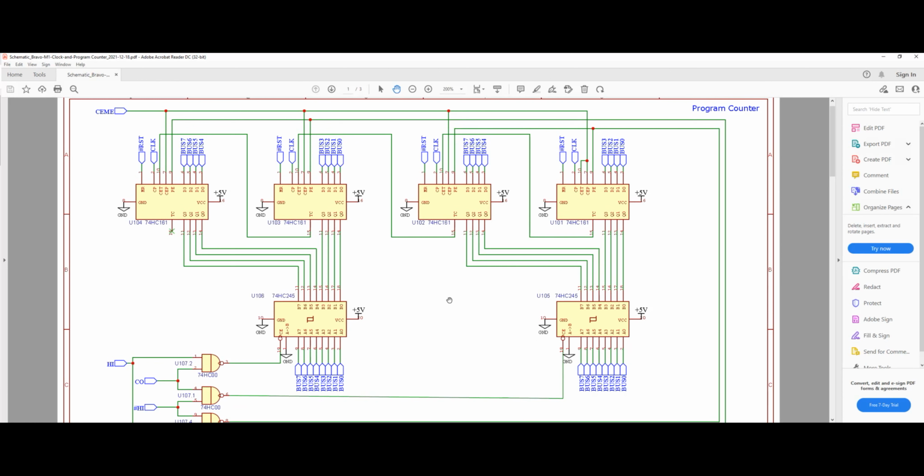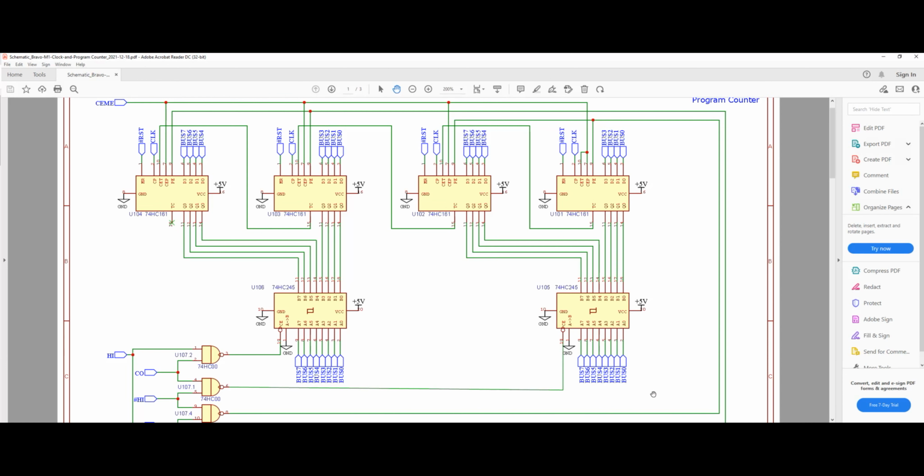So essentially, you're going to need 2 clock cycles for that to happen. That's why we have a concept of low byte and high byte when you're going from 16-bit to an 8-bit bus. Now, you may ask, could we just have the bus 16 bits? To be honest, it is possible, and you could just have a 16-bit counter and also a 16-bit bus. The only problem with that is that when you expand your bus to 16 bits, then you need to think about expanding everything else on the computer.